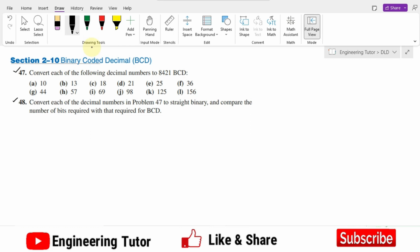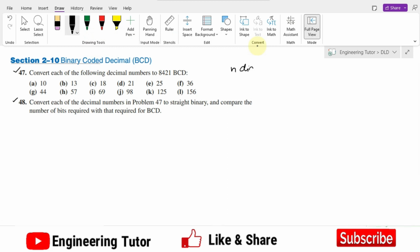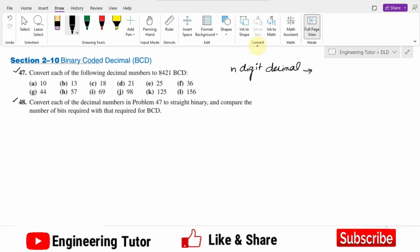So now we have to convert these numbers to their binary counterparts, and we have to see how many bits will be required in the straight binary and in the BCD, and what are the number of bits for each of the conversions here. Previously we have seen that for an n-digit decimal number, the number of bits required for the BCD will be 4 multiplied by n.